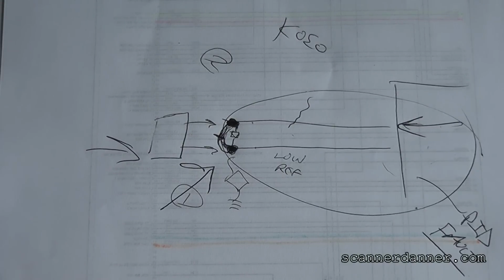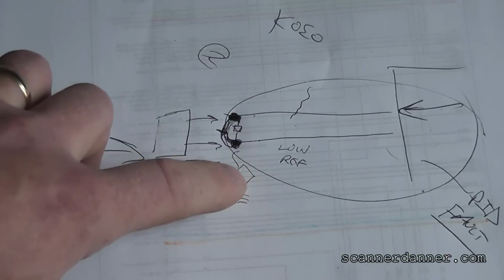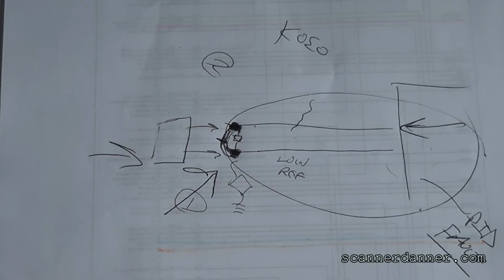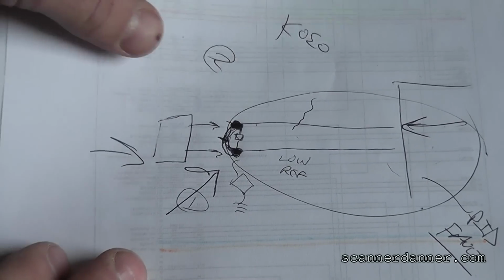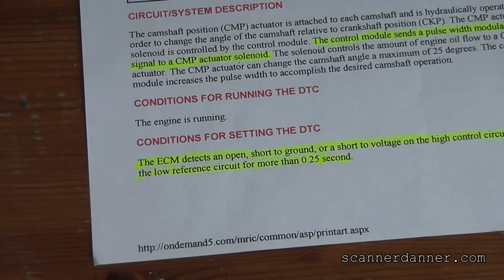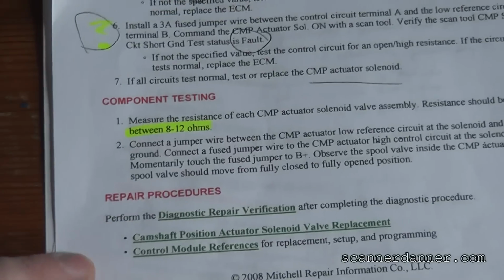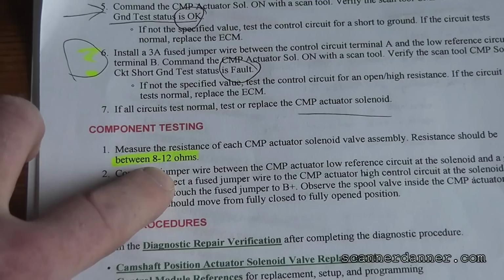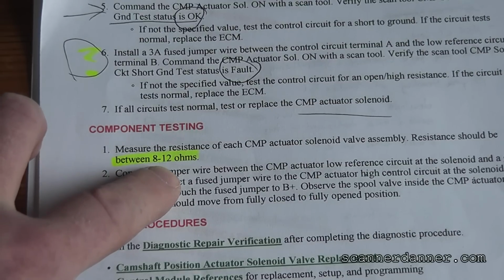A lot of you guys are concerned about me using my test light in ways that I do it. And guys, listen, my test light's about a 200 milliamp bulb. This solenoid carries way more current than that. How do I know that? Without even knowing this car, I'll show you. One last check on this flow chart right here. This solenoid should be 8 to 12 ohms. That solenoid is going to be very, very near 1 amp of current. Way higher than my test light.